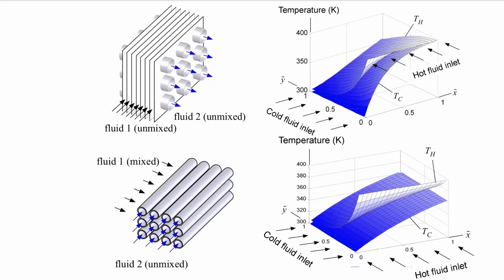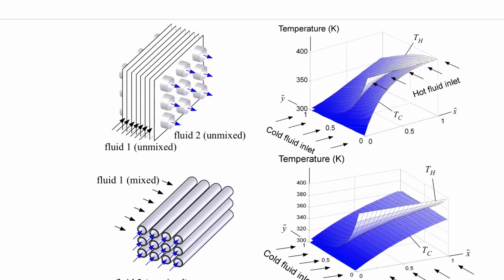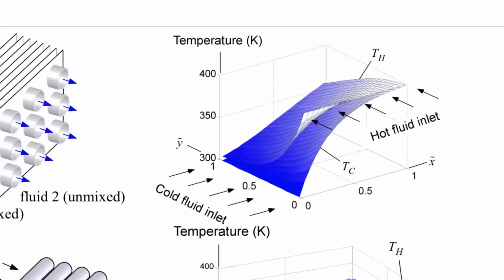So why is that? Well, let's look at our cross-flow heat exchanger up here. Let's call this maybe the hot side. So let's say this is an air conditioner. This is our hot side. We have a flow going through on the hot side. And then down here, we have cold air coming through. So if you don't allow the air to mix as it's going across the bank of tubes, what would you see if you were to plot the temperature? Here's a 2D temperature plot of this device, I'll zoom in a little.